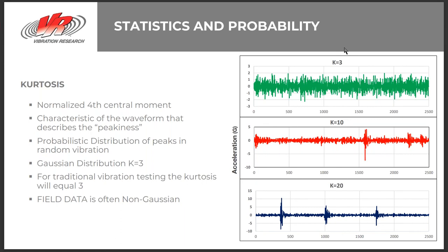So there are a few ways to evaluate different tests and run different tests with kurtosis, verifying that you are in fact not only getting those peak accelerations in the control trace, but also driving them through your product into the resonances, which is the true key of adding kurtosis into those vibration tests.